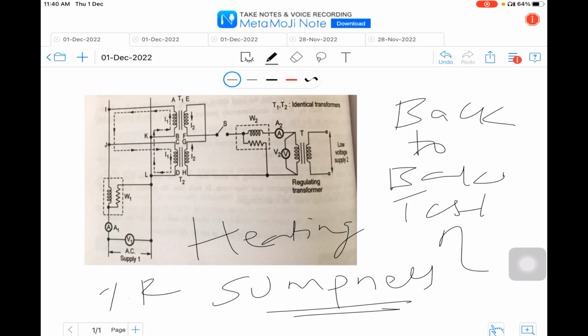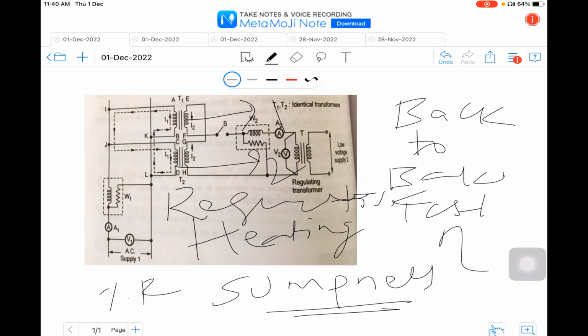So what they do is, large transformers can be tested for determining the maximum temperature rise by the back-to-back test. Another name of this test is the regenerative test. It is called the regenerative test, back-to-back test or Sumpner's test. It requires two identical transformers, transformer 1 and transformer 2. In the OC and SC tests we performed separately, using one transformer in each. Here, we use two identical transformers; this is transformer 1 and this is transformer 2.